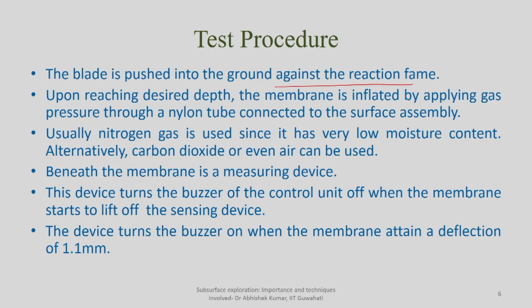And since you are not able to penetrate, you will not be able to understand how much is the shear strength or resistance offered by soil at different depths. So the reaction frame, again, you have to choose very carefully. Once you reach a desired depth, the membrane is inflated by means of gas pressure. So you apply gas pressure into the membrane, the bulge portion on one side, a steel membrane. There will be a nylon tube connected to the dilatometer, through which you will be applying pressure.